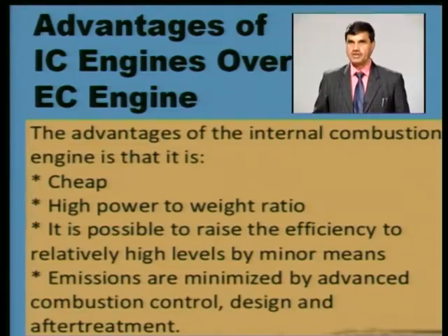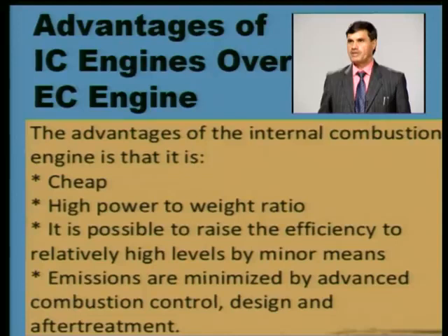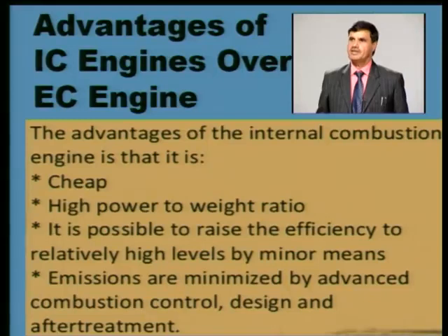Advantages of the ICE engine over the external combustion engine. Most of the engines which we are using these days are internal combustion engines, particularly when they are not stationary. For stationary purposes we can use external combustion engines, but for mobile applications we have internal combustion engines. They are relatively cheap, their power to weight ratio is quite high, and their thermal efficiency is significantly higher as compared to external combustion engines.